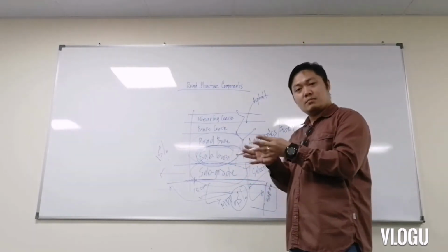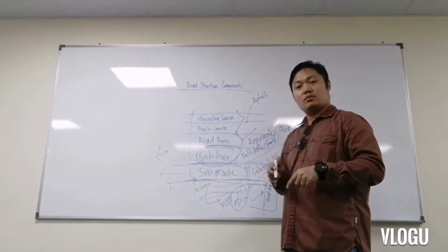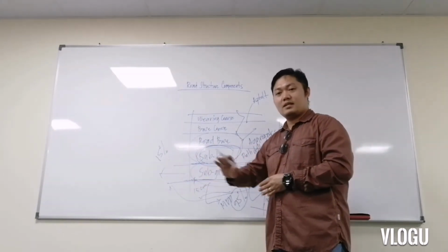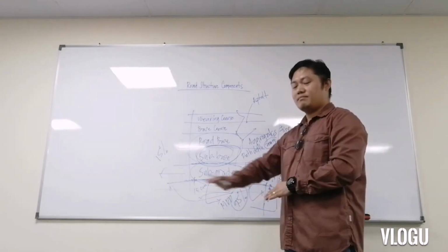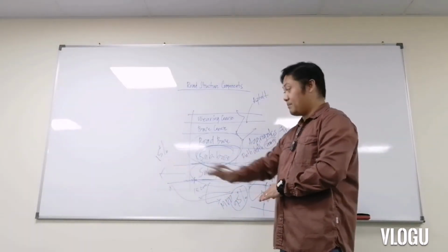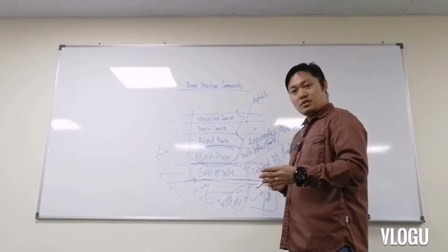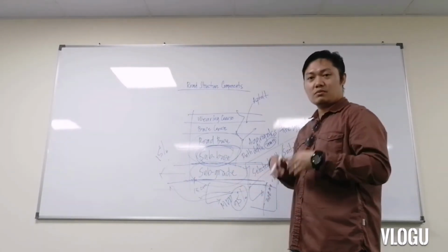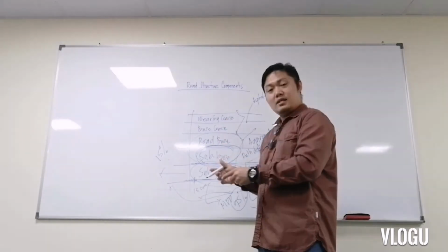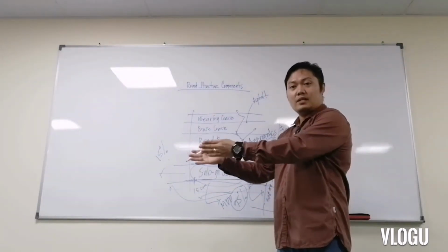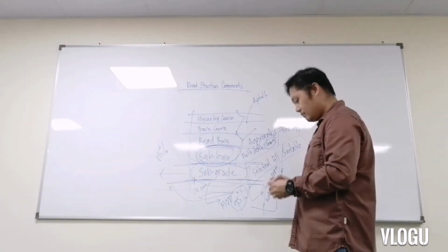If there is no sufficient space for the paver, sometimes we have to use only manual spreading by means of a grader, or let's say a Bobcat, in order to spread the subbase material. Why are we going to use the paver machine? Well, it's because we just want to ensure that the aggregates, the subbase materials, are properly spread without segregation.